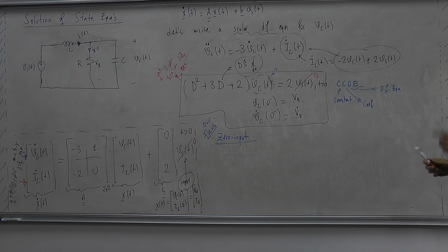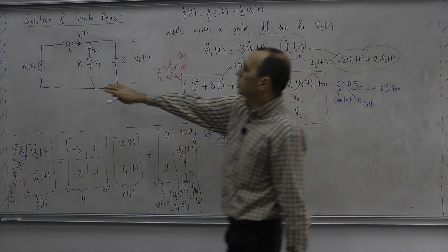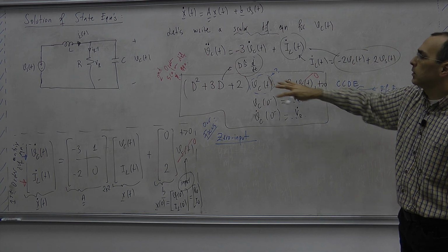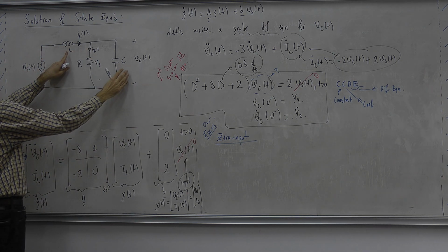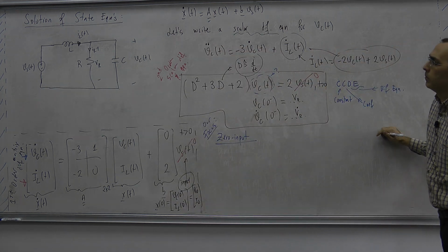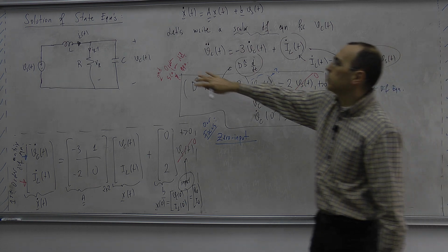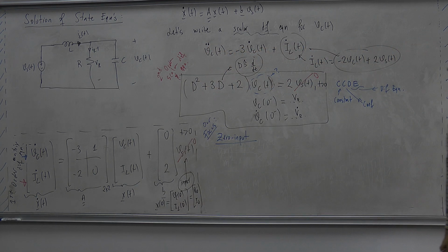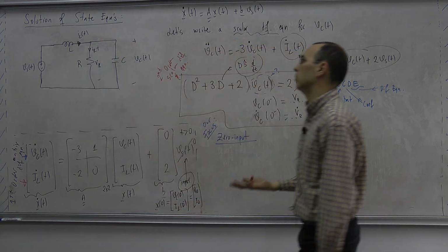So if the input is zero, that is also called the natural response of the circuit in the absence of external forcing, external input. So the system will be excited by the energy stored in these electrical components, and then the circuit will react naturally according to its nature to these initial conditions, and what we expect is that the initial energy stored in the system will be dissipating over this resistor. Okay. So eventually the current and the voltage, IL, Vc(t), should be going down to zero. Okay.